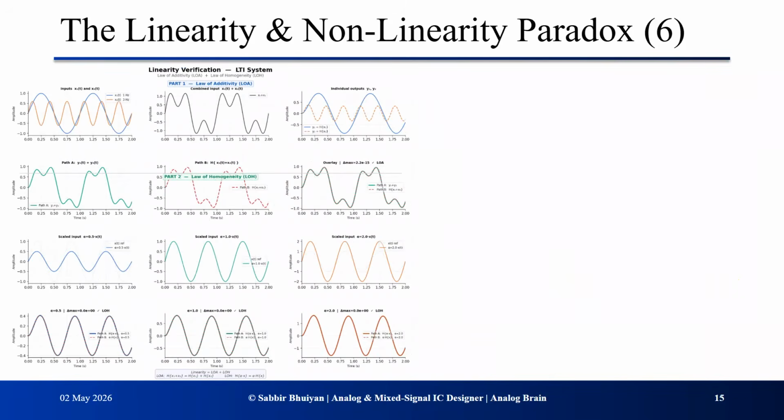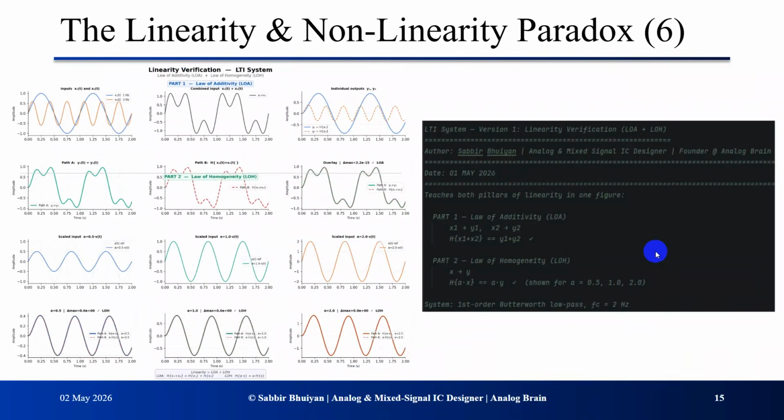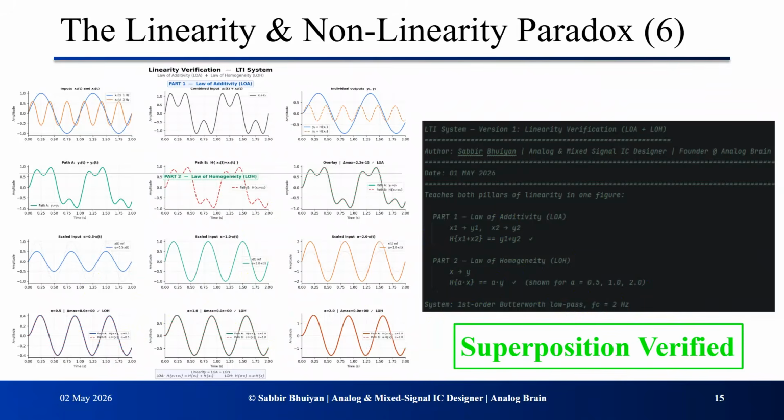And here is the full superposition verification, combining the law of additivity and the law of homogeneity in a single figure. Two sections: LOA on the top, LOH on the bottom. Here we have a first order Butterworth low pass as our system, with a cutoff frequency of 2 Hz. So the superposition is verified.